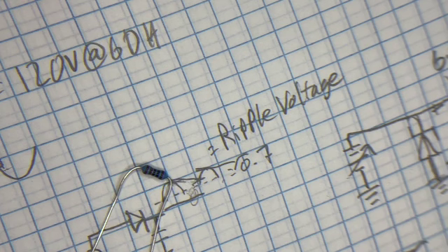So if at 8 ohms you're getting 100 watts and you drop that to 4 ohms, and this 100 watts is the rating of the amplifier, right? These amplifiers are rated based on their maximum power output. Means that 100 watts is for a matched load.